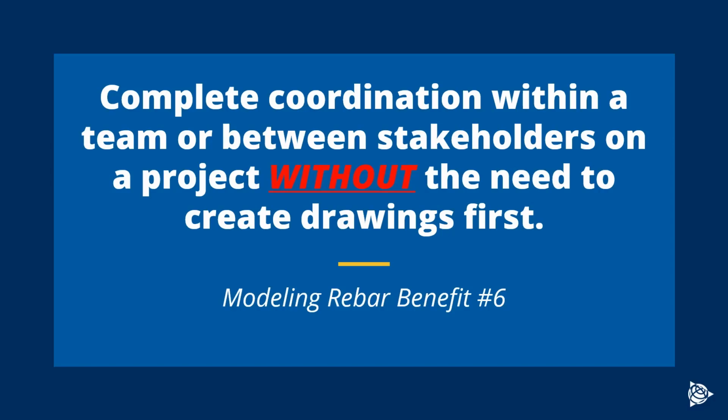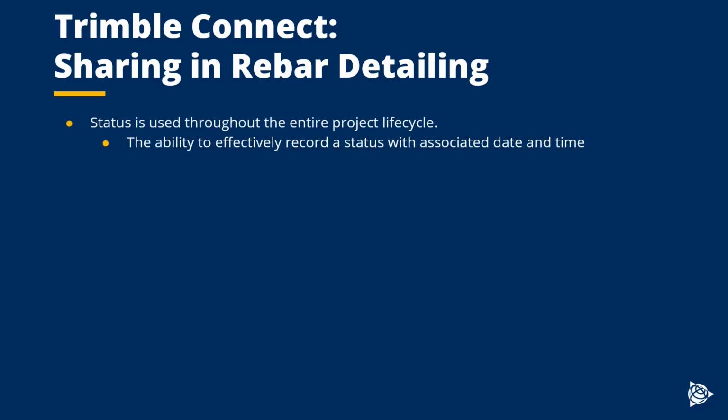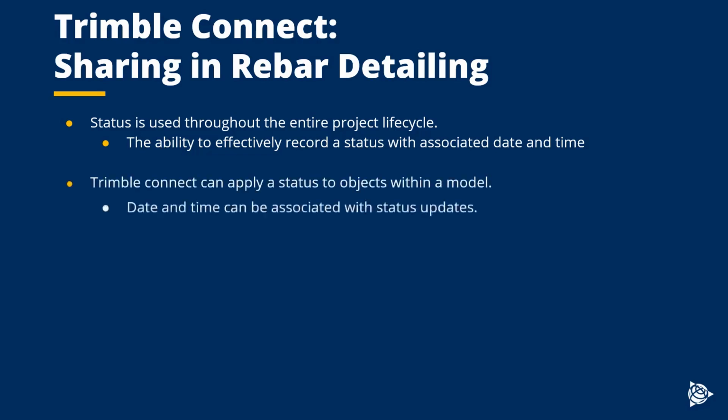So to round out this discussion on using a BIM model to collaborate throughout the process, we cannot forget to mention status sharing. We status every step of the process, whether it's from the initial concept design phase to pre-construction and to construction. And rebar is involved in a good portion of that. So we can status our bar in several different ways. Now there's a status sharing tool that's available within Trimble Connect that can actually talk directly back to Tekla Structures, or it can be communicated between Trimble Connect users on different platforms such as desktop or web versus mobile.